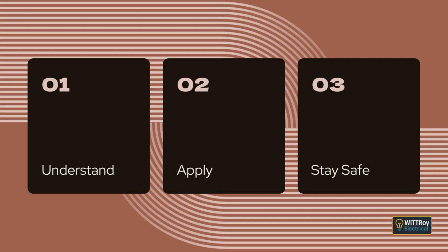Clause 3.8.3.4 Aerial earthing conductors. Aerial earthing conductors must be identified directly at each end of their run. The marking must clearly show that the conductor is an earth, either by using the letter E or by using an earthing symbol placed at the termination point.